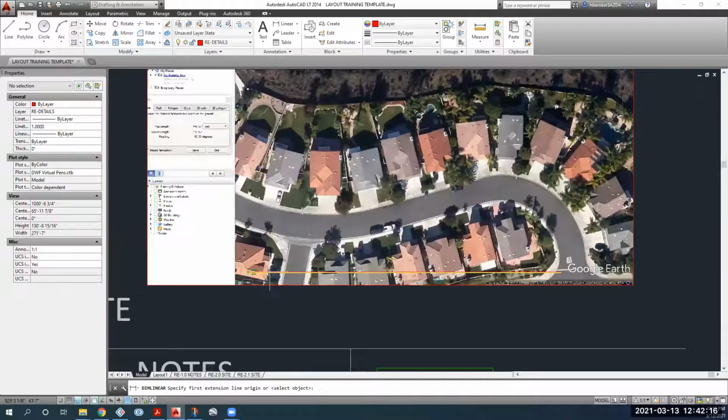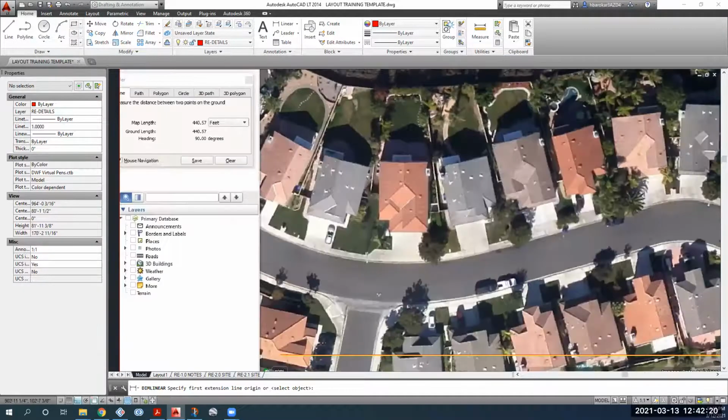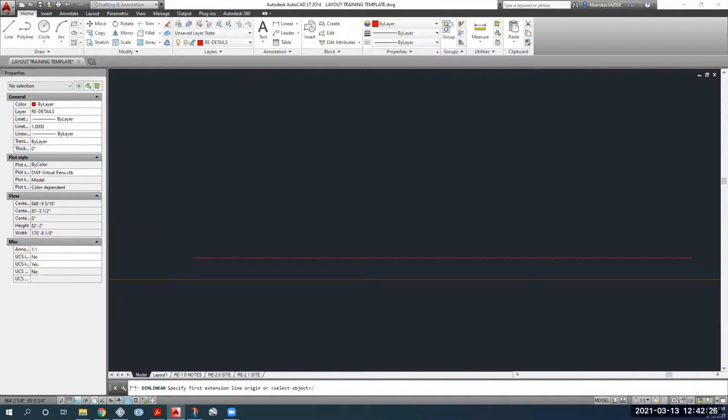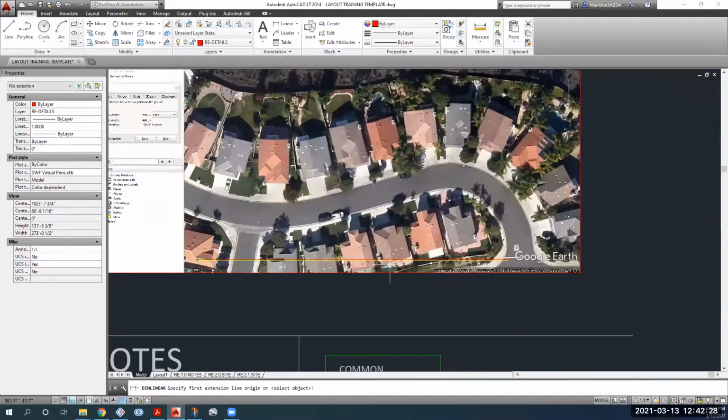When I took this line on Google Earth, I made sure that the orientation of it was 90 degrees, because pretty precisely the 90 degrees on Google Earth is the same as the 90 degrees in AutoCAD. So then I don't have to correct for tilt, or chase a line in a tilted plane. I can just work in ortho mode, and ortho mode is pretty simple to work in.